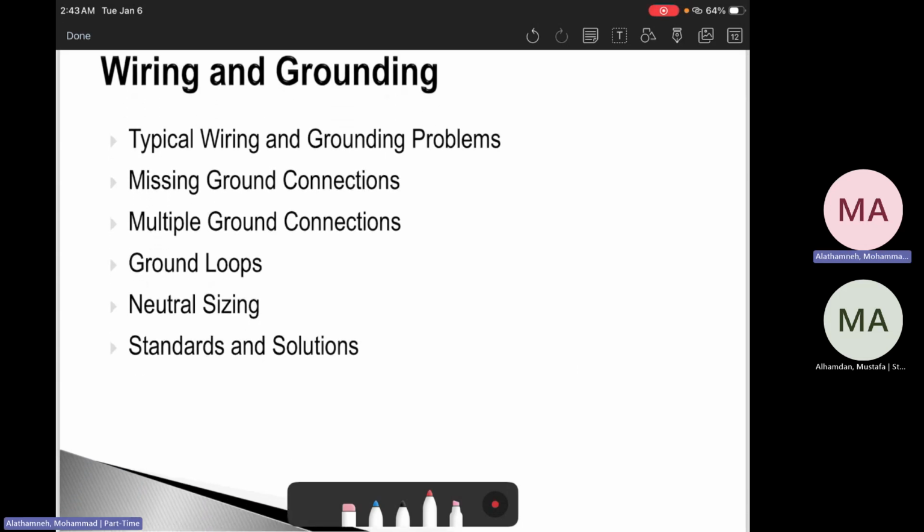Then we need to imagine as engineers that we have been called to a site to diagnose a problem, because we are engineers, we are problem solvers. They called you, we have a problem on site, and now you are on the site. The thing is not to start measuring THD and writing reports saying here is the report, we have a bad THD, so the problem comes from the utility side.